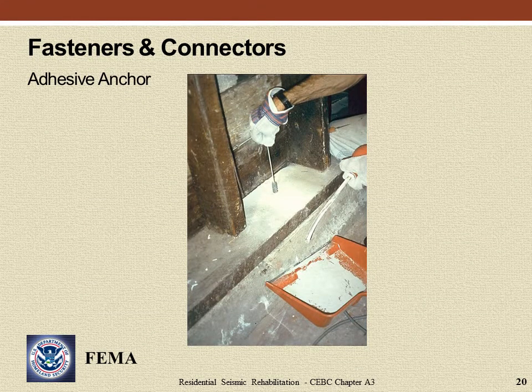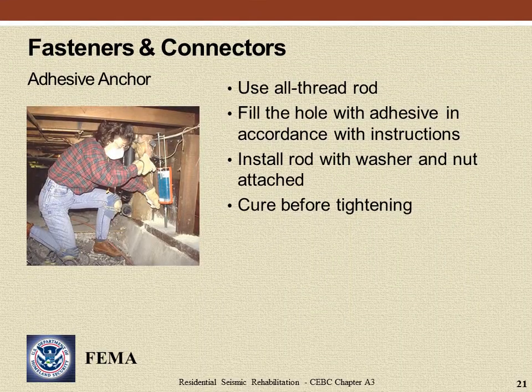Very important in anchor installation is proper cleaning of the drilled hole, generally using both a wire brush and compressed air. Where not cleaned properly, adhesive anchors will fail at a small portion of the rated capacity. When installing the adhesive anchor, it is important to use all-thread rod, fill the hole with adhesive in accordance with instructions, install rod with washer and nut attached, and cure before tightening.